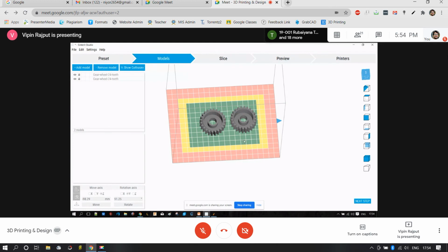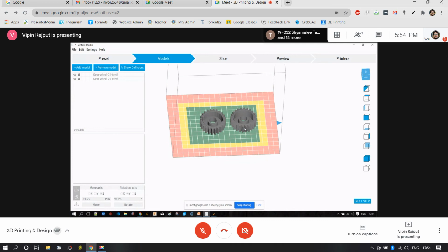So the software for SLS is very simple. In case of FDM or SLA, we are supposed to worry a lot about support formation, whether the internal supports may be formed, or whether a support may be placed where a surface requires good aesthetics. Then there is additional construction time and additional construction material.